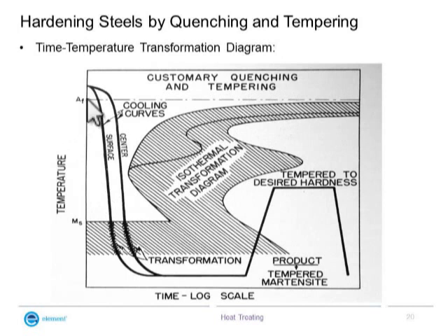Now for example, if the hardening is done by the quenching process, what is going to happen is, when you take the metal at a certain higher temperature and drop it into a quenching medium maintained at 30 degrees Celsius, the temperature difference is very large. If you drop it, the material gets a thermal shock. That thermal shock causes the material to crack. So we have to avoid the thermal crack.